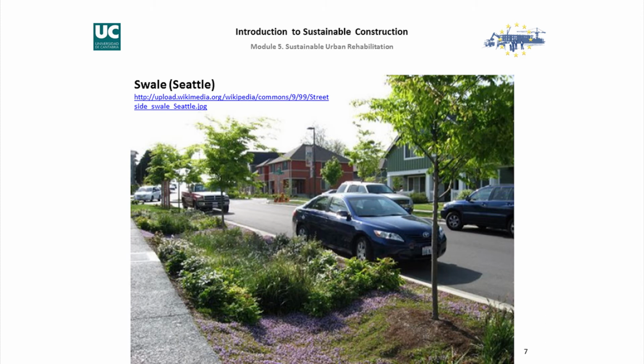Okay. With this green carpet, we are able to reproduce the advantages given by natural rivers, because we are creating an effect of filtration and also evapotranspiration. And finally, the transport of the rainwater is slower, so we are preventing problems like flooding in the city. This is quite difficult to do in the old cities or the city centers, because you need a lot of space in order to construct this. You need also a lot of space for the wetlands.